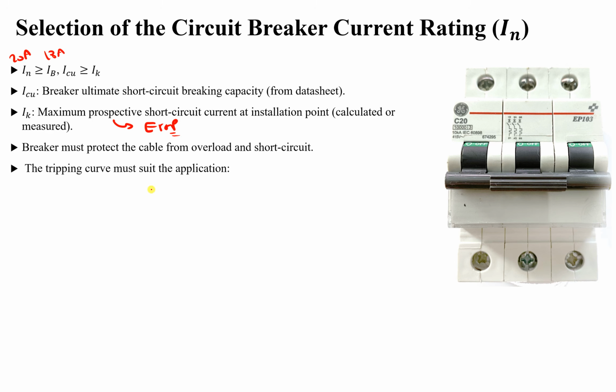Okay. Now another feature inside the circuit breaker, when we select it, is the curve. It can be A, B, C, D until K, if I remember. These curves represent the current at which it will start operating. What I mean exactly by current, you will see right now.